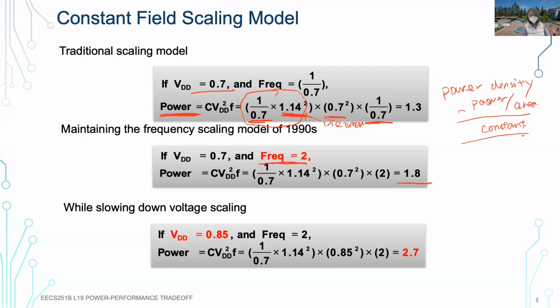What's the real issue? Why people missed standard scaling is that with the end of standard scaling, we cannot keep scaling down voltage anymore, right? We need to maintain a certain threshold voltage and also keep our leakage consumption in check. So we cannot scale voltage as fast as we like. We need to keep our voltage VDD at a particular level, so voltage scaling is slower. We still scale frequency pretty aggressively. So the power really exploded because now we cannot scale voltage faster. And if we keep pushing this whole frequency envelope, right, the power becomes really a problem.